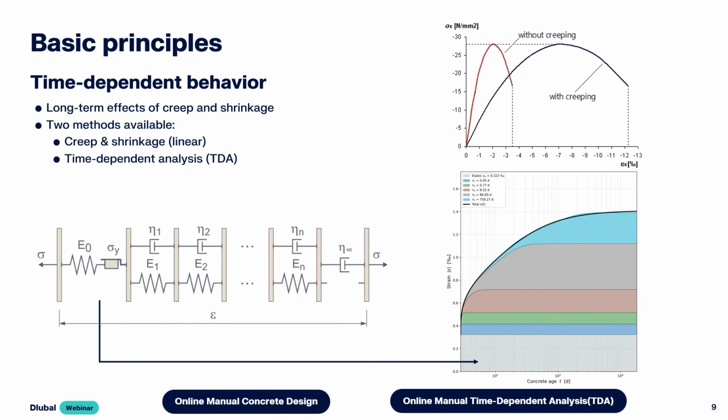First, there is an instantaneous deformation. In this case, it's a purely elastic deformation, which stays constant over time as long as there are no load changes. In addition, the chain elements are attached through the coupling of springs and a damper. Through the coupling of a spring and a damper, each element activates after a different amount of time. These are known as so-called retardation times.